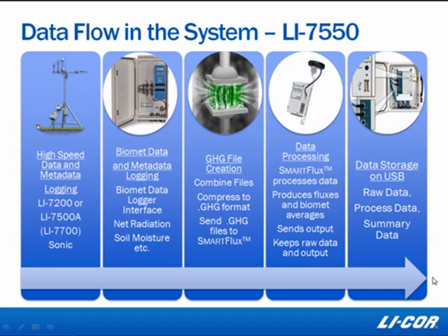As data is being logged, the LI-7550, if it has enough data for half an hour, zips it up and sends it to SmartFlux. But at the same time, it's opening up the next half-hour file and writing the data that's coming in from all the sensors into that file. So no, the data logging is not stopped for processing. We continue to log data even as the files are being processed.